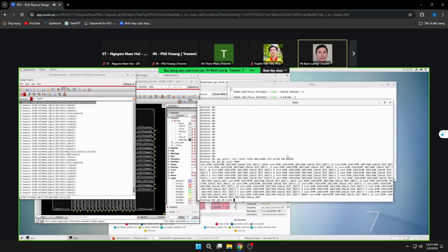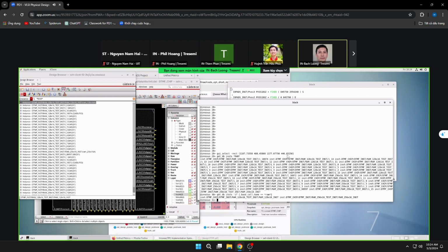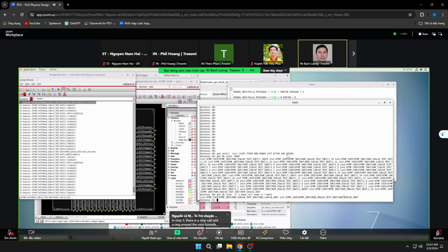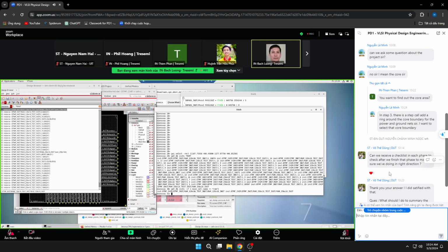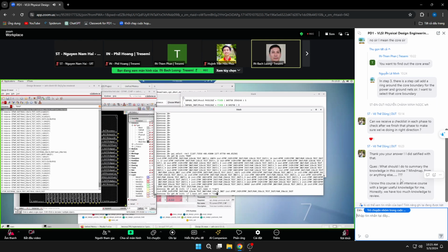So you can do -f, dot base_cell, which is basically the cell name, equal to star RAM or something like that. So it will come back with just the RAM names. As you can see here, the 2 instances are the same 2 instances that you see here, right? Likewise, you can do the same thing here with the ROM.